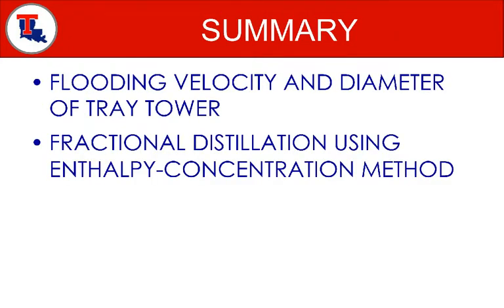And so basically today we looked at two main things, very important things. One is how to calculate the diameter of the tower, and second thing is how to interpret enthalpy concentration. All right. Next class, what we'll do is I'll bring in big charts for you guys to plot this enthalpy concentration data on, so we can do some hands-on design.